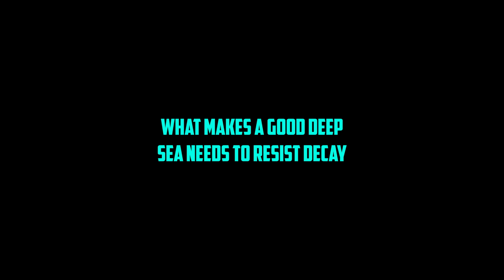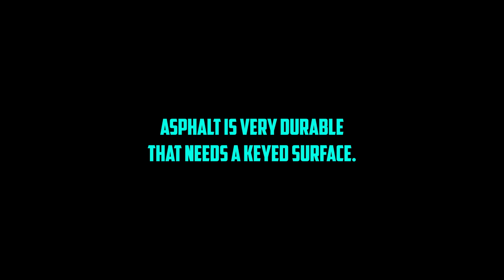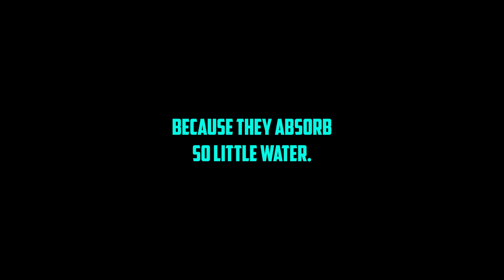Needs to resist decay, be tough enough not to tear easily, bond okay with mortar, and handle a bit of movement. Crucially, joints must be lapped at least 100 millimeters and sealed, and it has to connect properly with the floor damp-proof membrane, DPM. Mastic asphalt is very durable but needs a keyed surface. Even 2 courses of dense engineering bricks can work as a DPC because they absorb so little water.